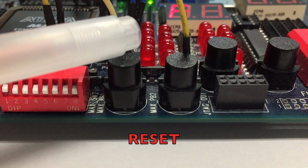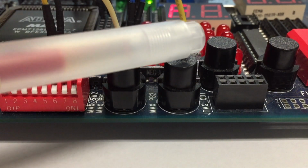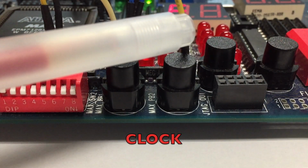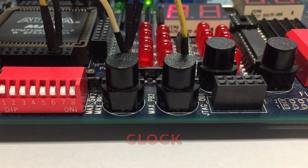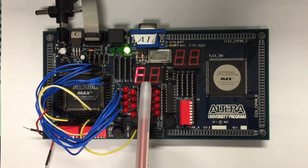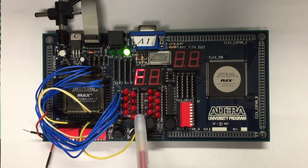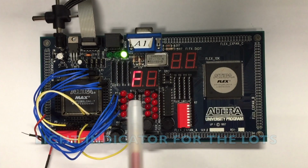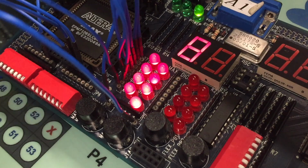The push button on the left is our reset button. The push button on the right is our clock button. We use 7 segments to display the number of lots available. This 8 LED represents the car park lots. If the LED is turned on, it indicates that the lot is free.